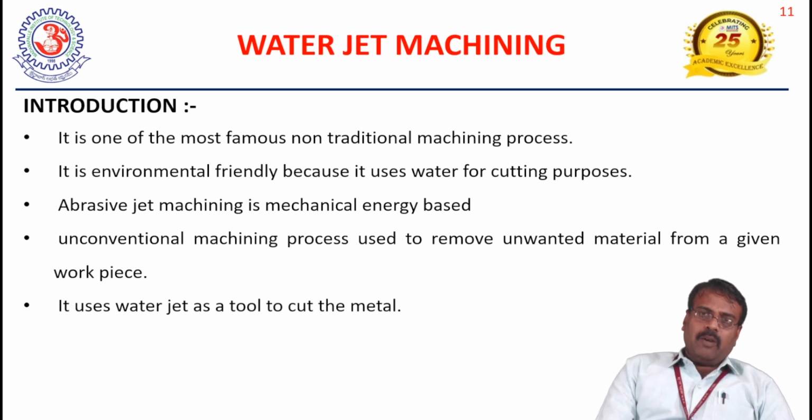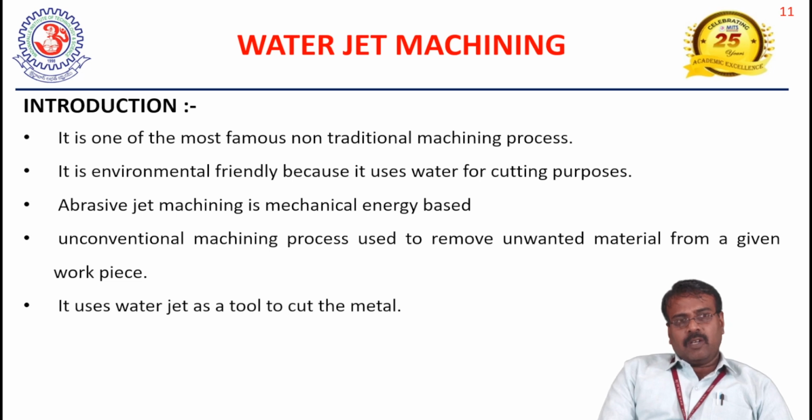What is the reason for using water jet machining? First of all, we are not going to affect the material properties. Whenever we use EDM or ultrasonic machining, due to heavy heat supply, the properties of the materials get disturbed.